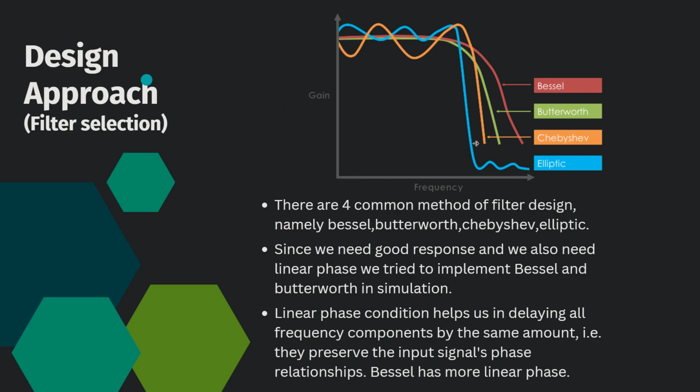So similarly we can see Bessel. Actually this diagram differs from our hardware implementation. In hardware we have used a buffer because our circuit wasn't responding, I mean it wasn't giving us the value we needed. So we took help of our assigned TA Vamshidhar sir. He told us it would be great if we could attach a buffer in between the low pass and the high pass, and it worked pretty well.